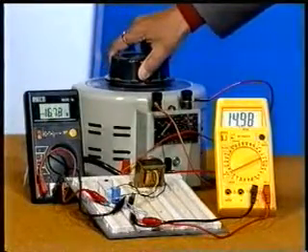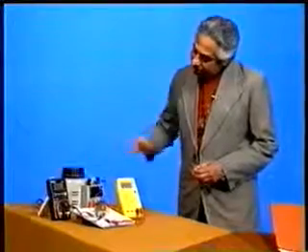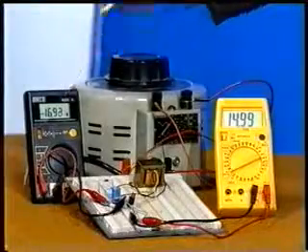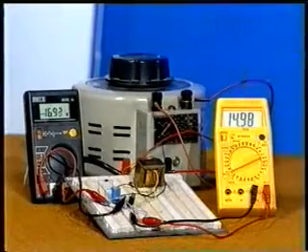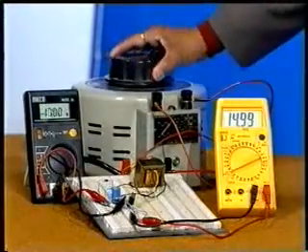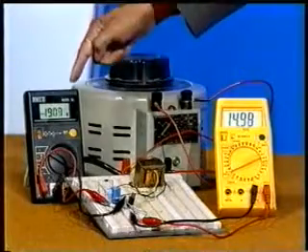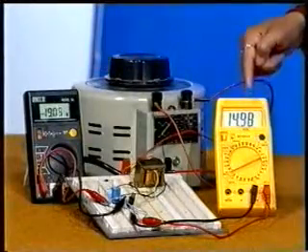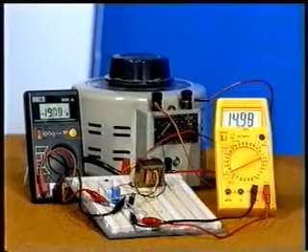Here when I give a 230 volt supply to it, the input is 16.93 volts DC and the output is 14.98. If I still increase it, you see the input is changing there, but the output here of the voltage regulator is not changing. Now what does it mean? This shows that it is a regulated power supply and there is no change in its output even if you change the input. Okay. Now the next component we are going to discuss is the 7 segment display.